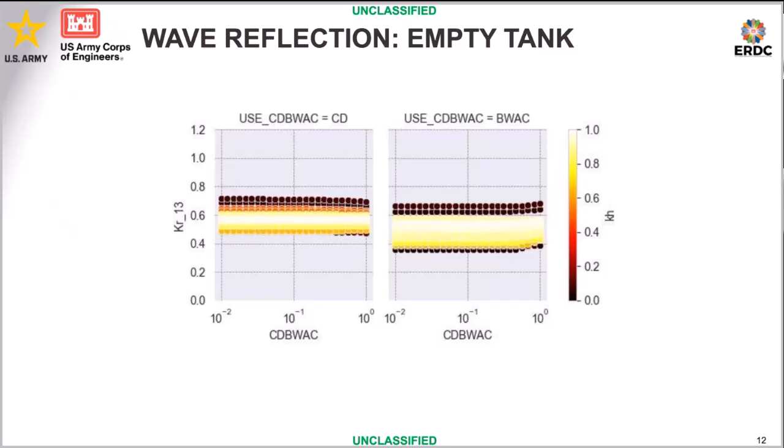And we're not seeing much change in that wave response, at least for this metric. So I always thought that a CD value like 0.002 seemed completely negligible, and for the most part I feel like it is. Even 0.02 might not be doing what you think it's doing.